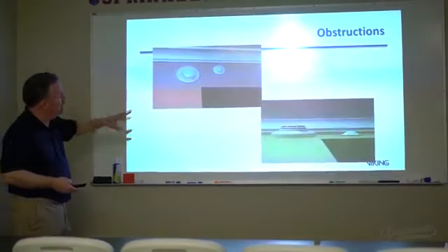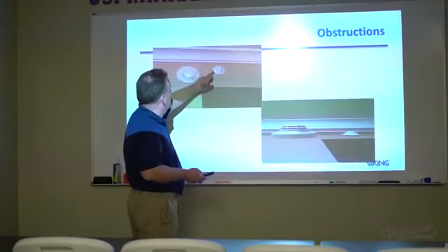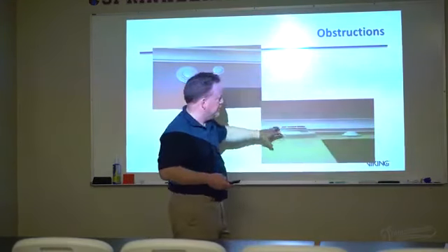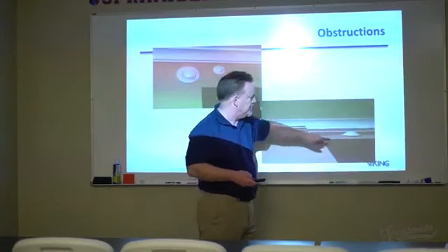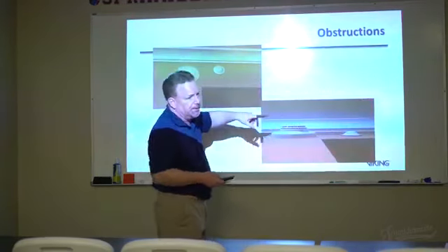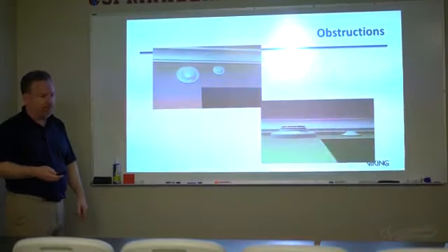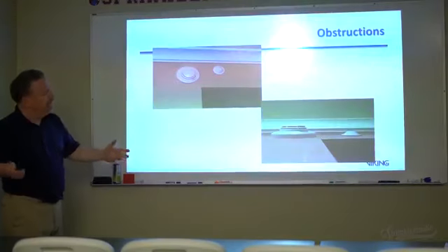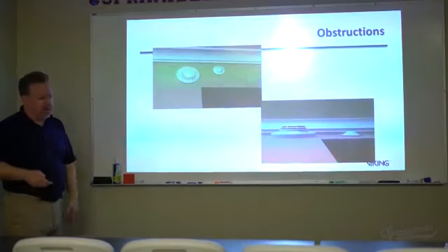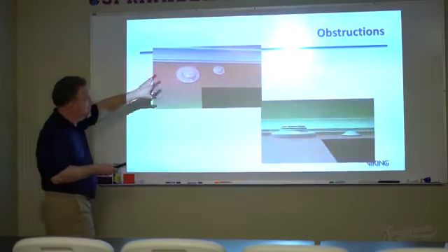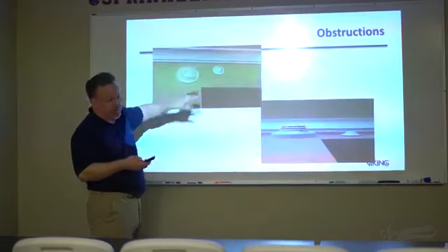Okay. We also have obstructions that we need to be aware of. This is, I think, a 3.5-inch minimum distance now. So this is the problem: we put a nice big detection device right next to my recessed, my concealed sprinkler. It could be an obstruction to the spray pattern development down the wall, unless of course it's greater than 3.5, I think, or 4 inches away from that unit. So again, just be aware of that when it comes to recessed sidewall sprinklers and obstructions that are non-continuous on that particular wall.